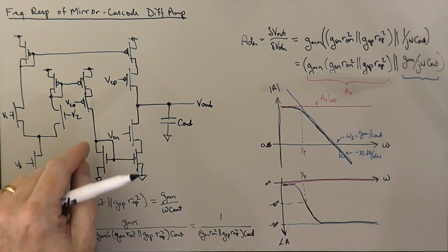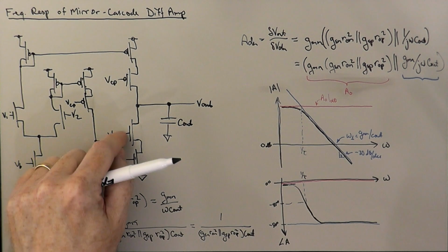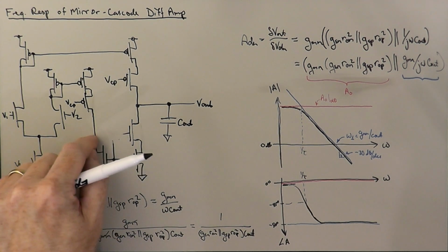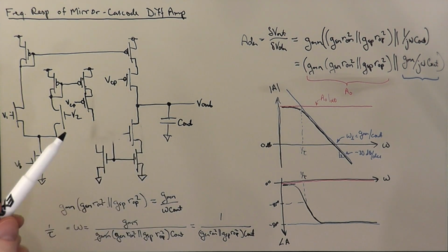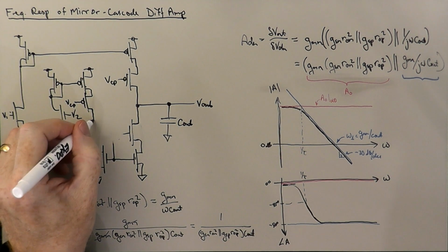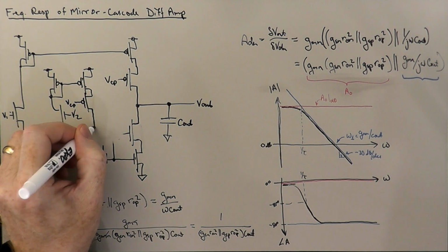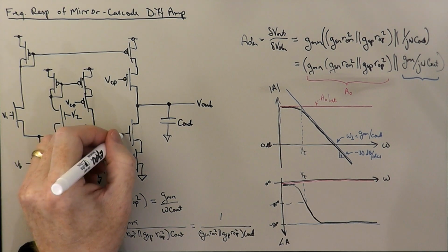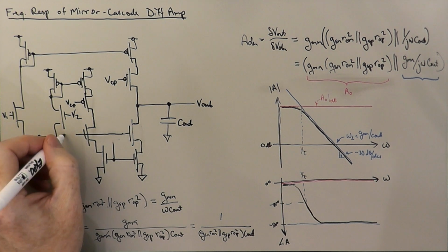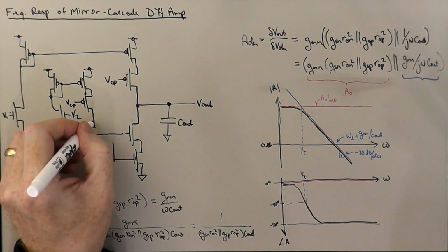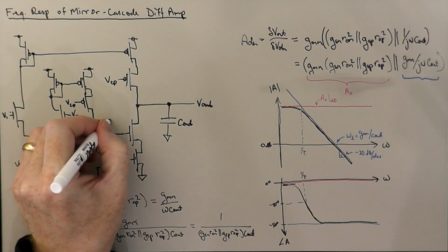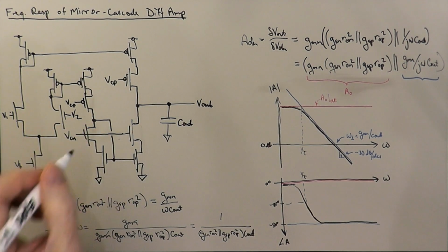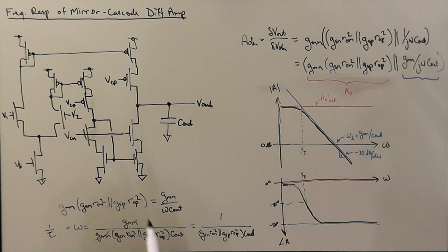Okay, we would probably also want to do something a little fancier down here with this NMOS current mirror. We would probably want to add a cascode transistor on the input branch as well, VCN, and then basically make our diode connection around the cascode transistor on the input branch.